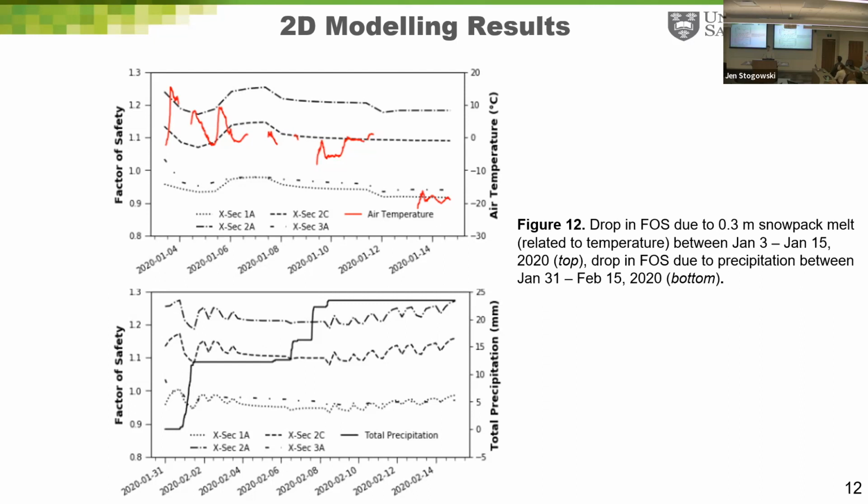And stability analysis was also then conducted at quarter-day increments for each period to document the change in factor of safety. So both scenarios indicated potential changes of up to 10% in the overall factor of safety. On the other hand, the seasonal variation in the river accounted for about a 20% change in factor of safety. So therefore, the near surface soil water content variations can have potentially large impacts on slope stability, especially if they coincide with the seasonal minimum river level.